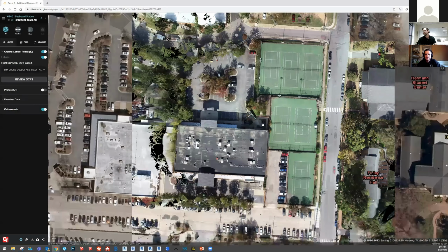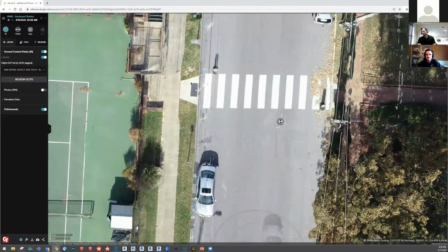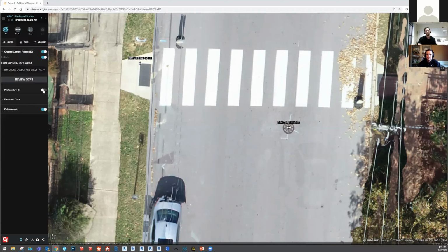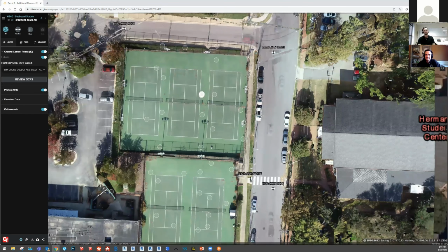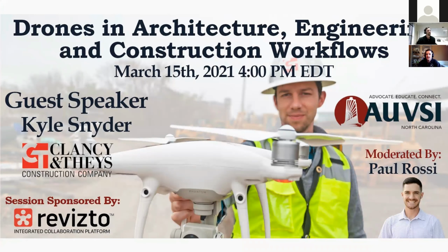Yeah, so like a little example, you can get actual coordinates of whatever known elements or targets are out there, and then when you put them together, you basically calibrate a number of photos, you locate it. So when it's generating the 3D geometry, it's pinned to actual real space. Because the tolerance of the GPS, what is it, in feet, I believe, right? Just like the satellites out of the box. Yeah, so you're going to see about 3 meters is probably going to be your high for a tolerance, so right about 9 feet. Like anyone knows, if you've used an iPhone to take photos and look at the map, they could be all over the place. Essentially, it's the same thing with this. The satellite gets you in the vicinity, but if you're really looking for that tolerance, you really got to tie it to control.